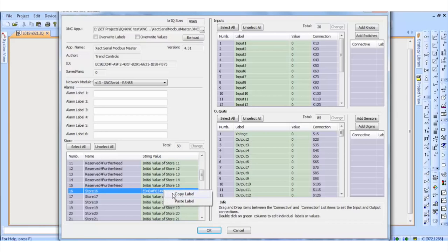So we can copy that, we'll do Control C and Control V here. So we go back to the start of this string. We've added another meter and we'll call it address 41. So we'll change the address to 41. This function stays the same. These registers are the same because it's the same meter. I still want 10 values from there.